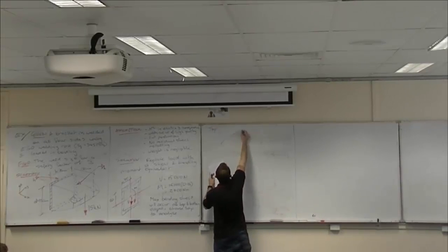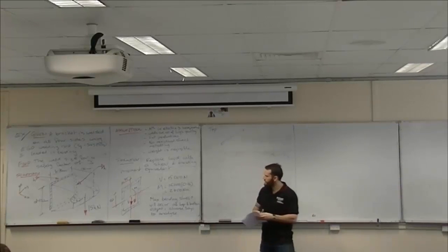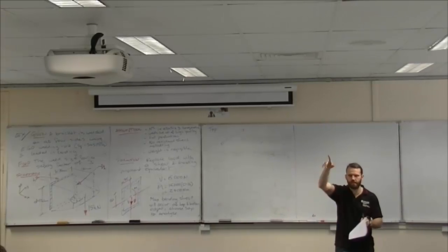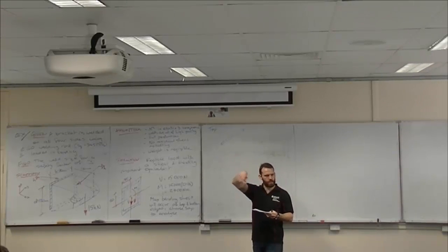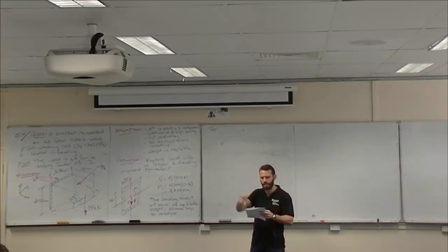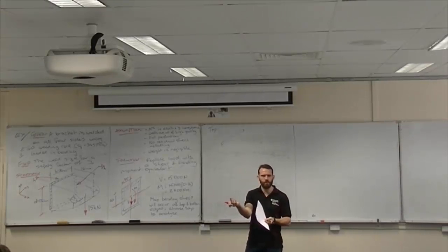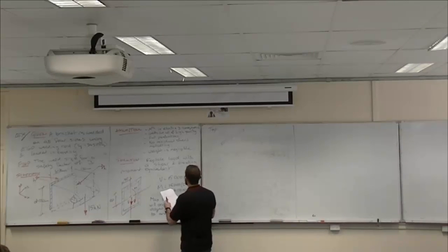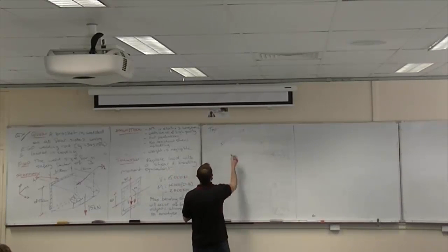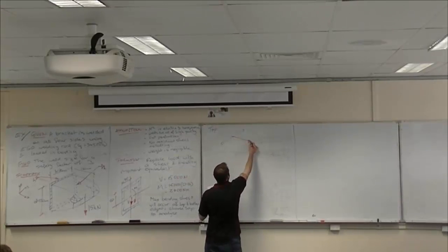I'd like to sort of redraw it and then draw my stress vectors on it. I can redraw the whole thing, or I can just draw a top edge. Remember yesterday we drew those stress vectors on the whole shape of the weld, and that was largely because we had a couple of potential candidates. Did anyone analyse that other point? Was that more or less critical? Did anyone do it? At some stage between now and next lecture, I advise go and do that other point. It would be a good study for the torsional thing, and I'd like to know whether it's more critical or not. I'm pretty sure it's not, because I ask that every year and no one comes to me and tells me I was wrong.